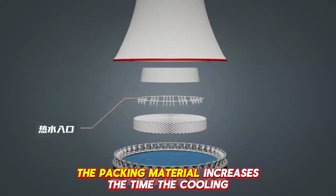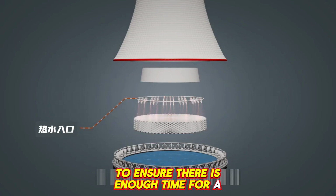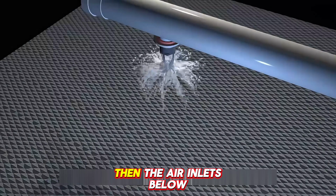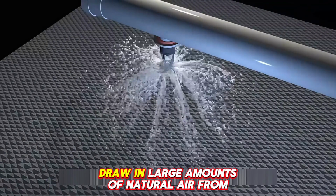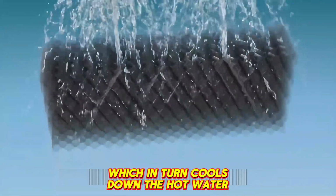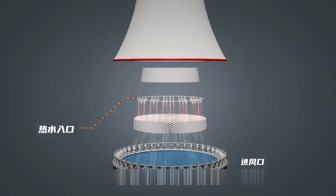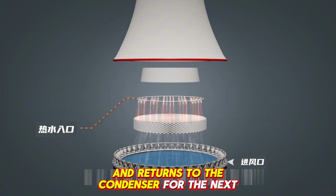The packing material increases the time the cooling water stays to ensure there is enough time for a thorough heat exchange. Then, the air inlets below draw in large amounts of natural air from the outside, which in turn cools down the hot water. After being cooled, the water flows through outlet pipes at the bottom and returns to the condenser for the next cycle.